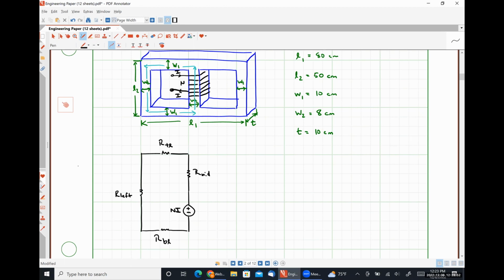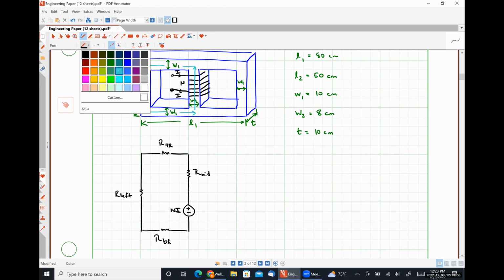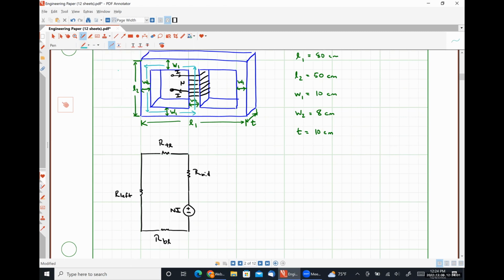Okay. Now, actually, we'll finish drawing the equivalent magnetic circuit, and then we'll talk about a couple of things here. Now let's talk about what the right path is going to see, right? So our flux is being driven up through that middle branch, and it can flow to the left, but some portion of it can branch off and flow to the right. So we're going to have this bit, and then this bit, and then this bit, and then the flux that is branched off to the sides comes back together and flows up, just like we would expect current to do in an electrical circuit.